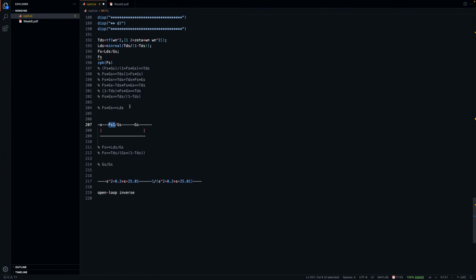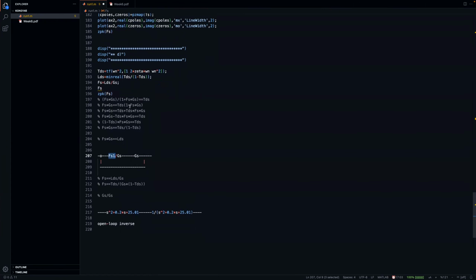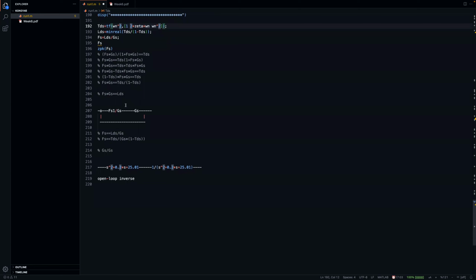If you want to, of course, have ramp type input tracking, you should update T(s) here, so that you have basically 2 times zeta omega_n s plus omega_n squared. So that in that case, you would have s squared at the origin. You can just toy around with it and see if it's really the case.